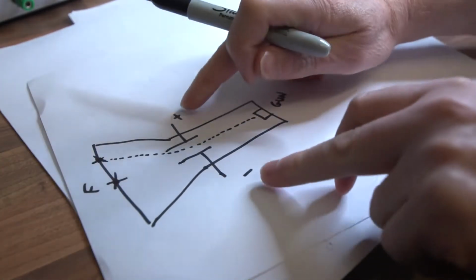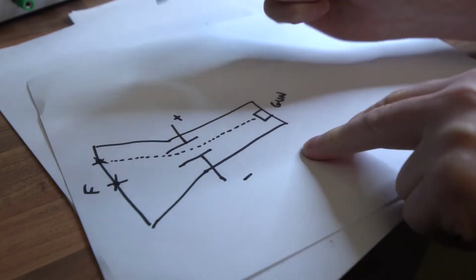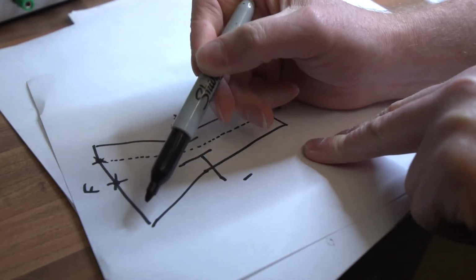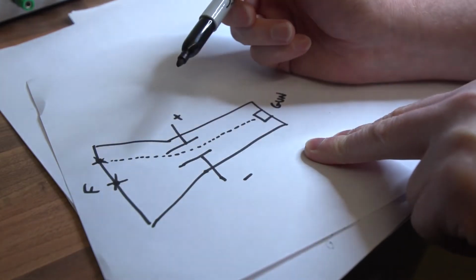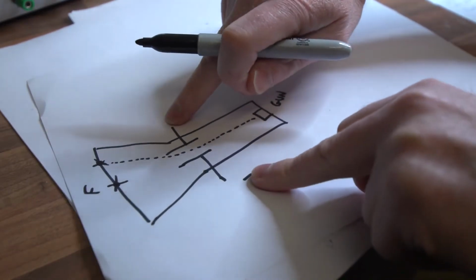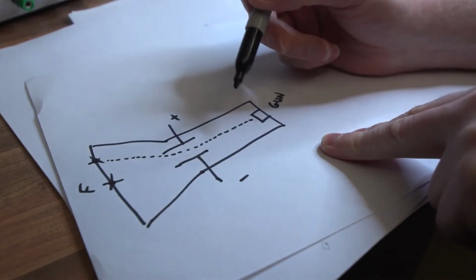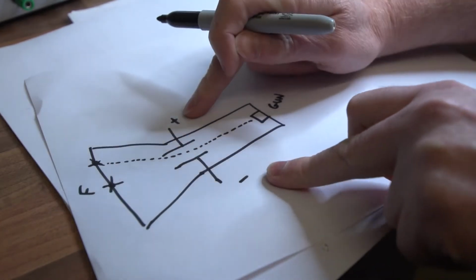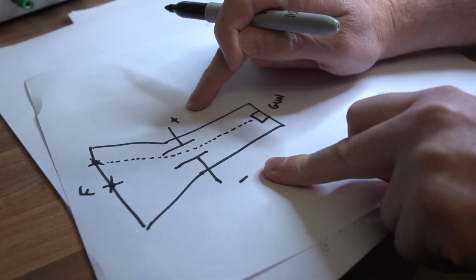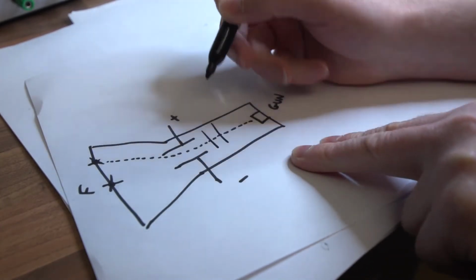If you swap them around, then the beam would go down. So by changing the difference of voltage across these 2 plates, these are the Y plates, you can move the dot up and down, which is what we just did earlier with the 9-volt battery. It's exactly what we're doing. You're not putting 9 volts across the plates, you're actually putting a few hundred volts across the plates. There's an amplifier inside of the scope which amplifies the input to the voltage that's needed for the plates, but it's calibrated. The X plates are basically exactly the same, but the other way.